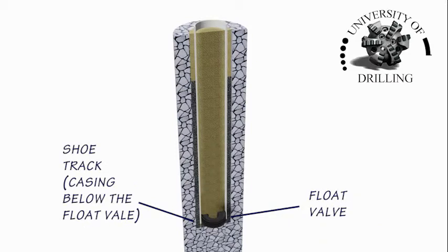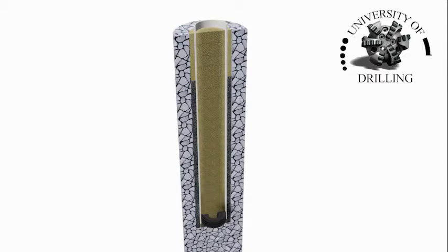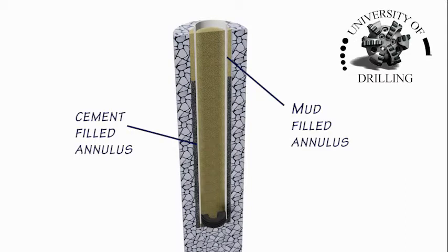A one-way valve, or float valve, in the casing shoe, or end of the casing string, allows the cement to be pumped from the casing's end and prevents the heavy cement from re-entering the casing. Cement that flows out under the casing turns the corner at the casing shoe and travels up the space, or annulus, between the casing and the borehole it is within.